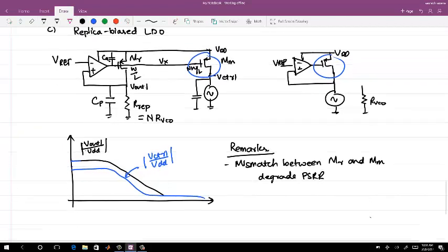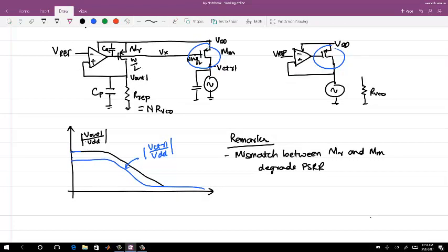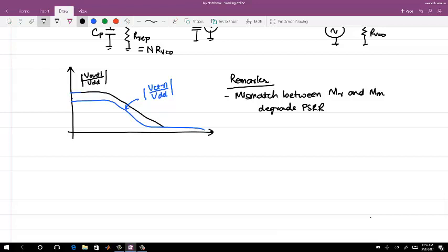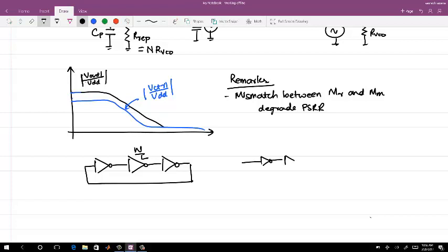So the other thing is that now I am using a VCO as a real load. If I want to use a replica of the VCO, what shall I use? No, right? Okay, let me put it this way. If you are using a replica VCO, the two VCOs cannot run at different frequency if you want a real replica of the VCO. So here, if this VCO is of size W by L in the replica, this is main VCO and replica.